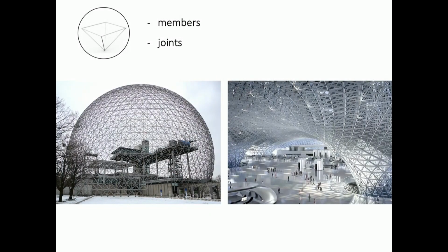So we can see when we look at the development of space frame structures that there's a shift from this to that. So what's this, what's that? This is a singly curved geometry, and it has a constant curvature. What that means is that even if we just had a pencil and a paper, we could define the angles of the members, we could see what geometry we would get, and we would have the same angles on the top layer and the bottom layer throughout the whole structure. So the same joint throughout the whole structure, same member lengths, easy to build, great.